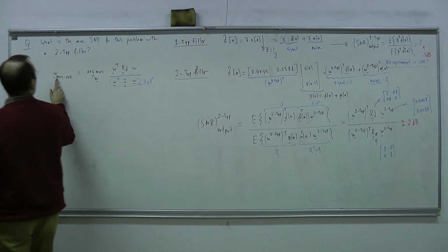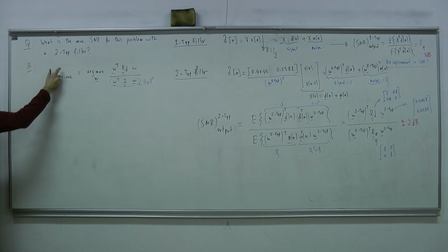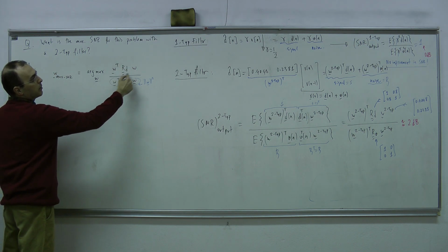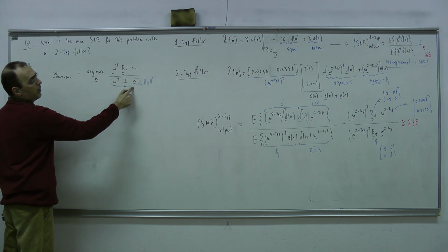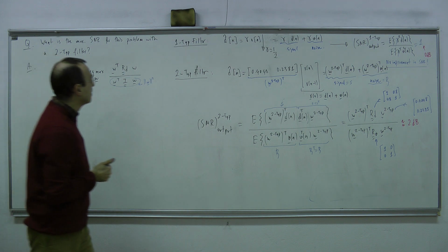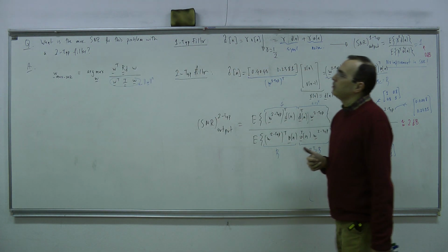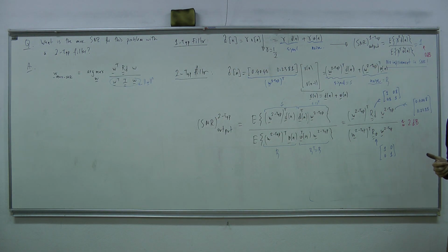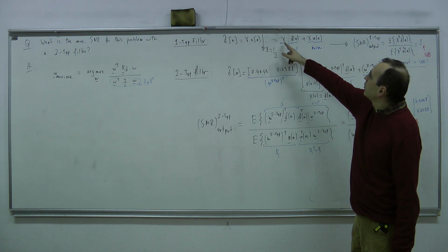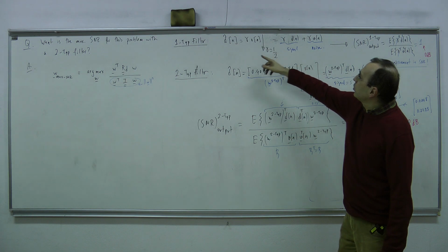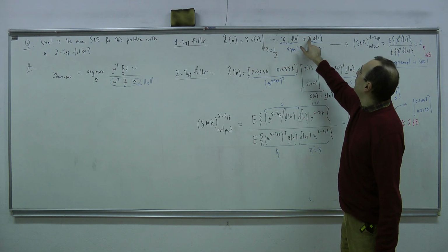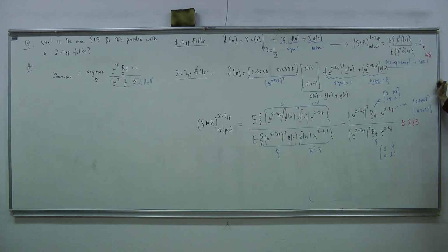Now here's the issue. If you multiply any W vector by a scalar, let's say by gamma, then the numerator is multiplied by gamma square, and the denominator is multiplied by gamma square. Again, those gamma squares cancel. So you see that this vector cannot be defined uniquely. Actually, that's what we have seen in one-tap filtering. Because if I multiply this prediction result by an arbitrary gamma factor, SNR doesn't change.